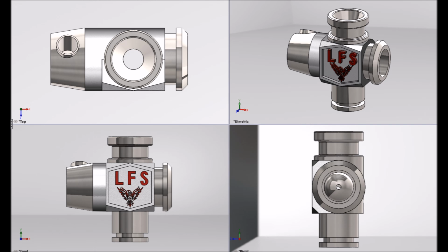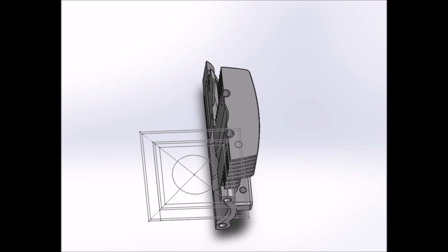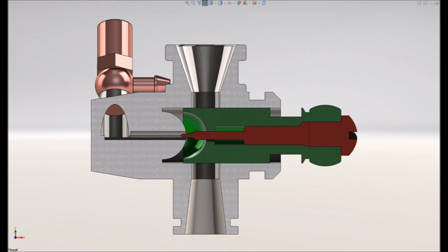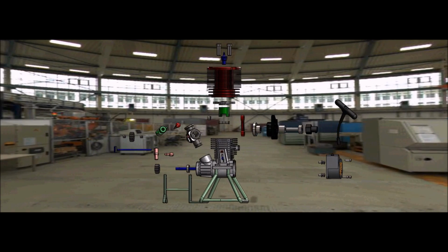To create the parts, I used swept, extrude, revolve, lofted, shell, mirror, 2D and 3D sketches, and much more. Extrude, swept, and reference geometry were the three features that I used the most. In some of the parts, I created sketches that guided every other sketch. I placed extensive detail on each individual part. Every single part of my assembly was designed to fit together.